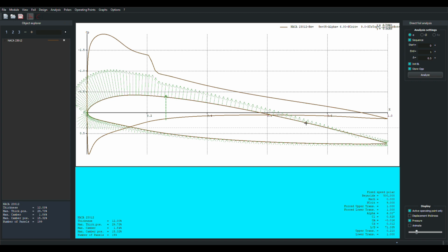The other thing is that they can turn left or right, go inboard or outboard. Well, on a tapered swept flying wing, going inboard is difficult because of what the flow conditions are like, but going outboard is quite easy. And that's why we have span-wise flow on swept wings. The flow is trying to find the easier way out, and that would be span-wise.